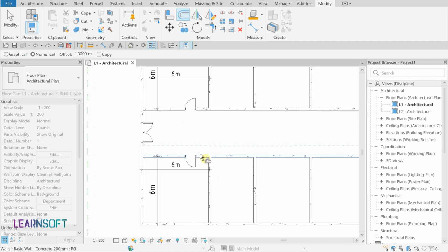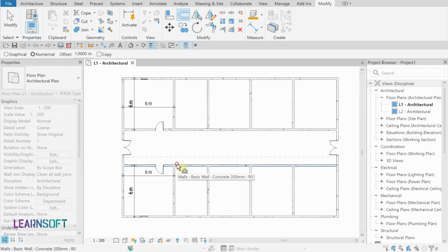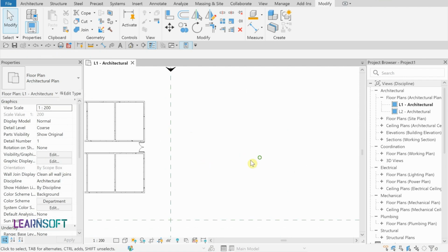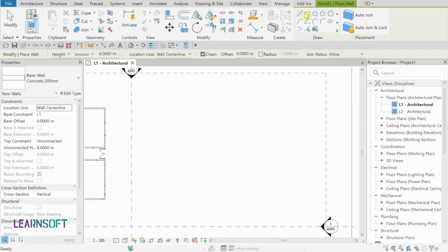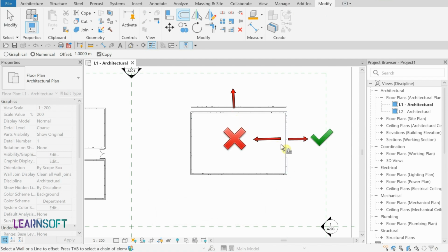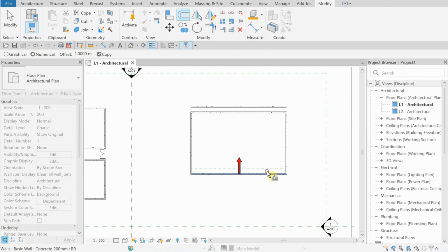Let's practice this point. Move the wall of the corridor with 1 meter offsetting. As you can see, the wall and attached doors move together. There are other tips about offsetting that I tell you. When you do offsetting one after another, the side that you select as offsetting will be the base. It cannot be changed to one outside and one inside. If you want to change the direction of offsetting, you can finish the operation, then click the Offset tool again.